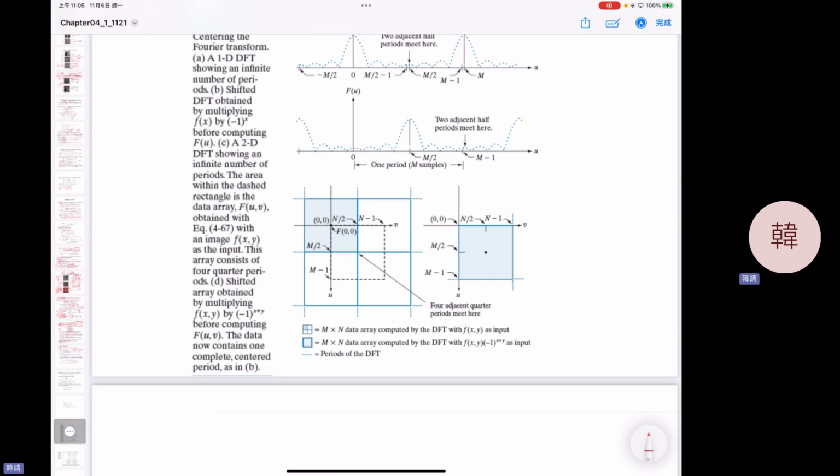And this one, what's that? It's also Gaussian, but upside down. So how do you do that? Easy. 1 minus the low-pass filter. So if this is H low, this is 1 minus H low. You can get this one, right? It's upside down. Use a constant minus your low-pass filter, and you get this one. So what's that? It's a high-pass filter. So you can see the center will be removed, and the higher frequency part will be maintained.